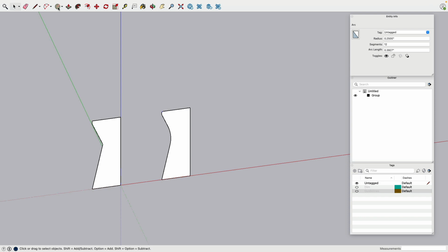Okay, we would like to revolve this. We need a circle. Again, the up arrow, left or right can switch the orientation. There we are. And then here, this I delete. I select the ring and then 64, so it's nice and smooth.